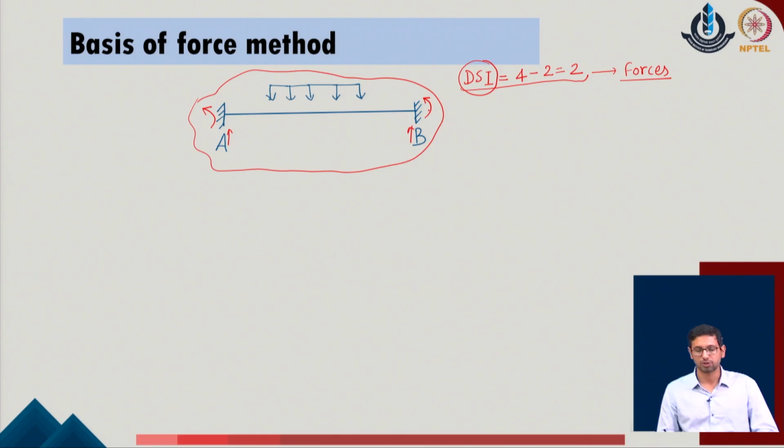So, over here, as we consider that the given system is subjected to some load and we understand that the system is statically indeterminate with degree 2, what a user can do as a first step is reduce this problem into a statically determinate problem, which means that out of all those 4 reactions in the given system which are making the system indeterminate, we will try to remove any 2 reactions and consider them as the redundants or the extra reactions of the given system, so that the system can be converted into a simple statically determinate problem.